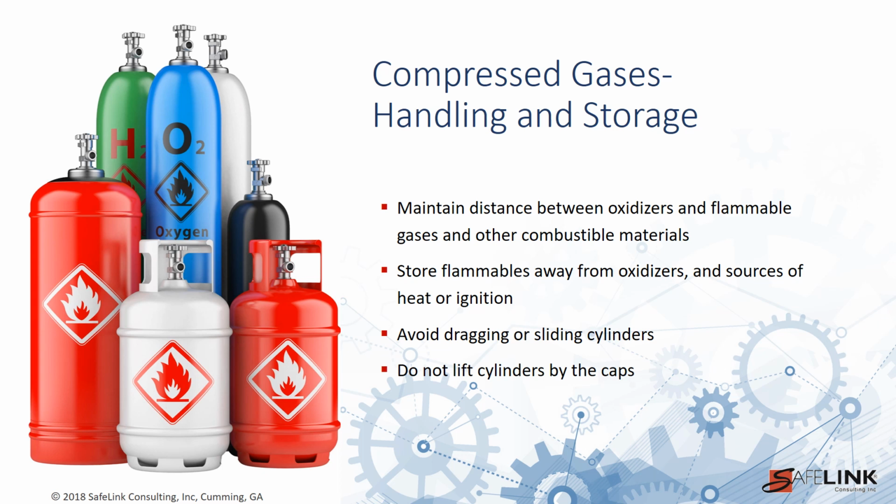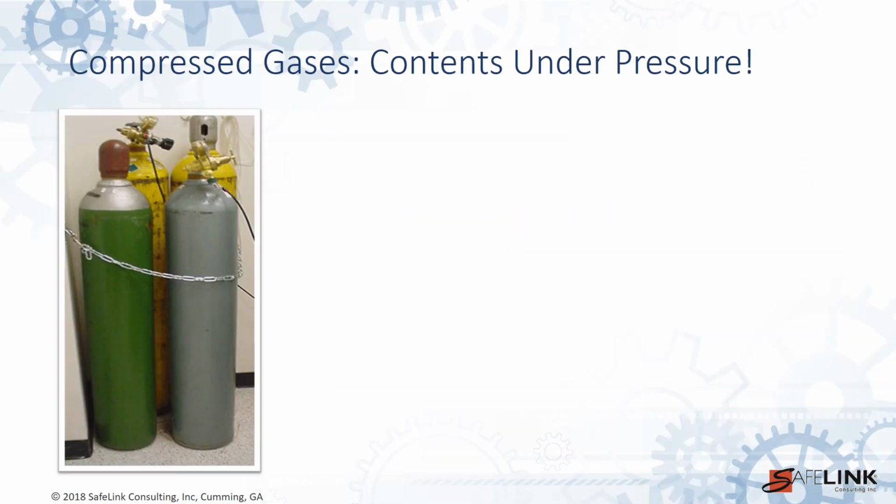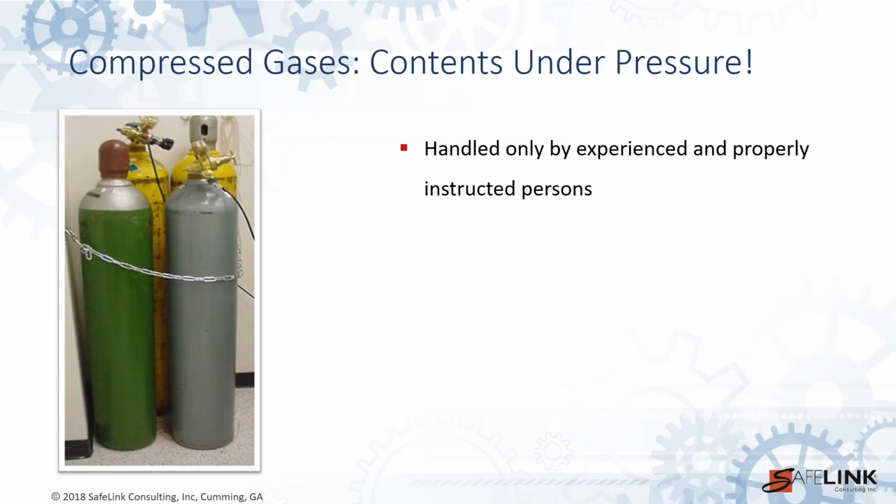Avoid dragging or sliding cylinders. Do not lift cylinders by the caps. Compressed gases should be handled only by experienced and properly instructed workers. The user should first identify the product within the cylinder from the label or stencil on the cylinder before use. If the cylinder is not labeled to show the product contained, then the cylinder should be returned to the supplier